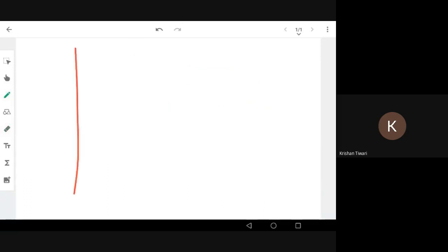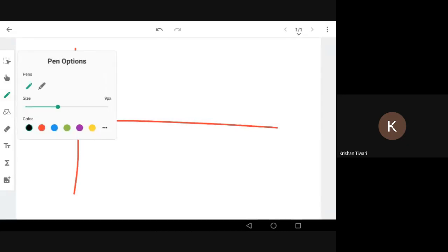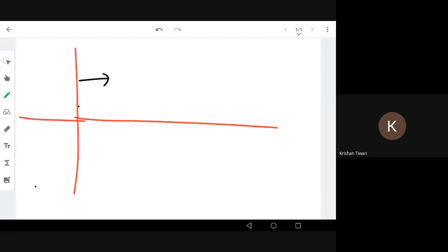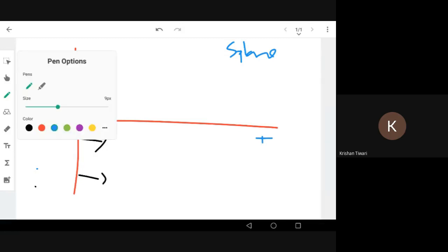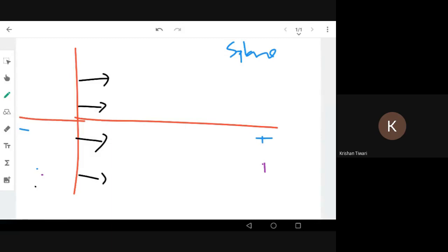Whenever, in the S-plane, the roots of the characteristic equation lie on the right side of the S-plane. This is the S-plane. We have negative here and positive here. Here we are talking about the denominator. We have a numerator N(s) and denominator D(s) of the transfer function H(s), and D(s) is called the characteristic equation.